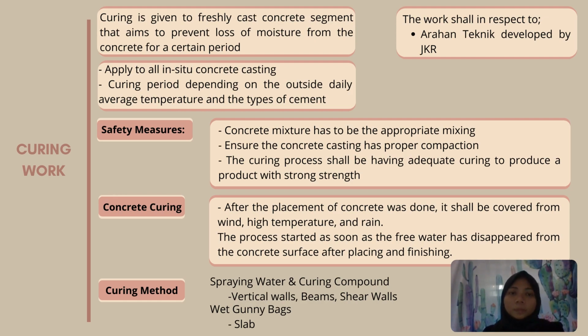Next method statement in structural part is curing work. Curing is given to freshly cast concrete that aims to prevent loss of moisture from the concrete for a certain period. So the standard that we have followed is Arahan Teknik developed by JKR, and it is in curing work applied to all in situ concrete casting. Curing period depends on the outside daily average temperature and the types of the cement.